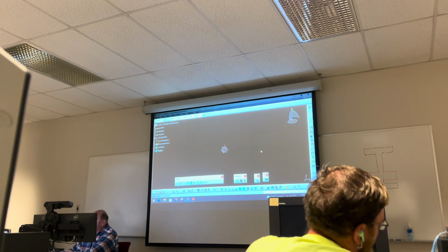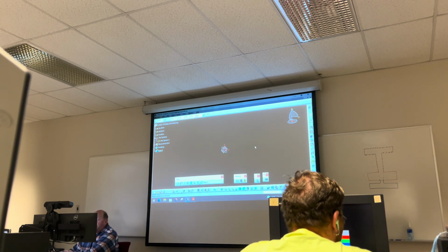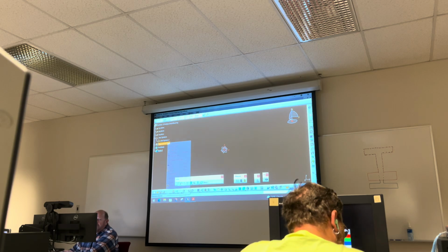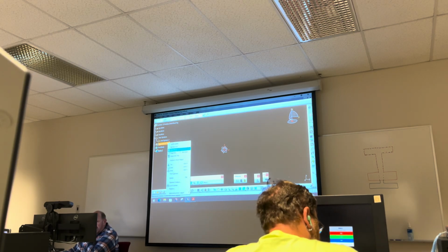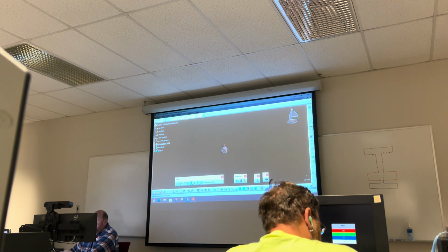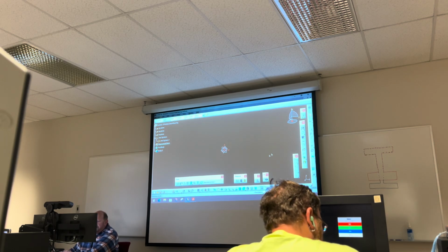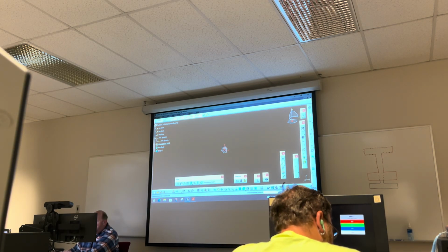So the first thing I wanna do is define where, I think what I'm gonna do is go up here and do it in a geoset just to figure out how I'm gonna lay the part out. So I'm gonna say define work object, and the geoset, I'm just gonna use for reference right now as far as what I'm gonna construct. And let's see what the rest of my commands are. Definitely need line, point, and curve.